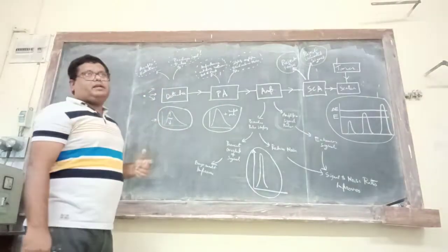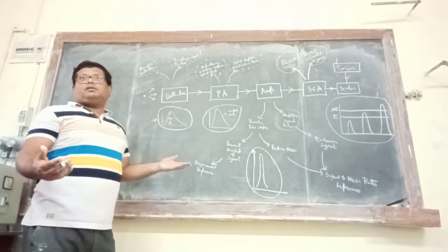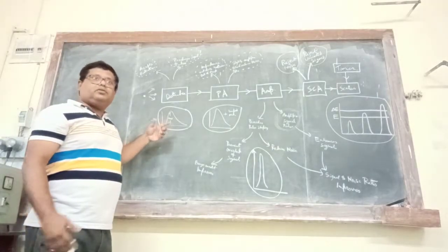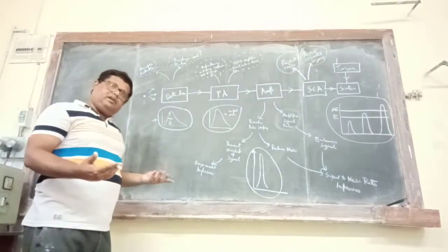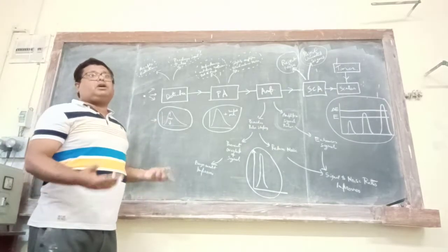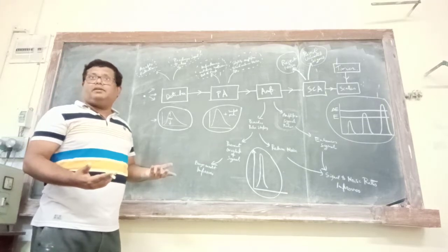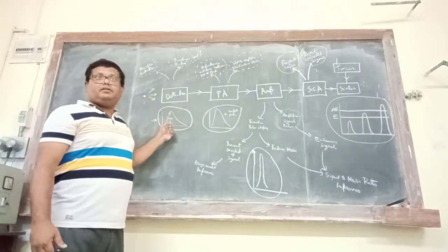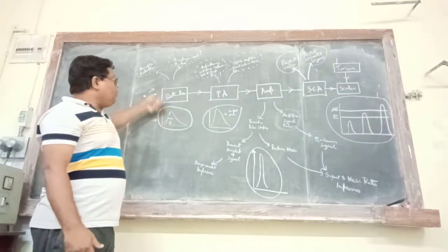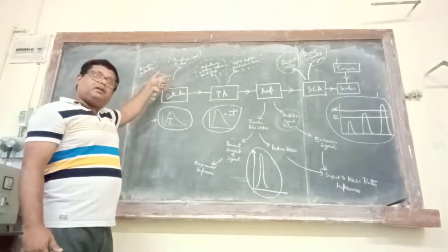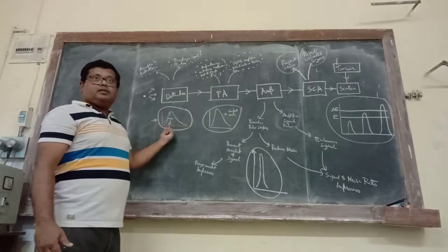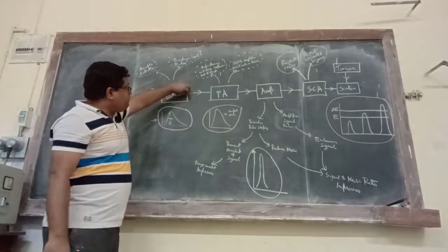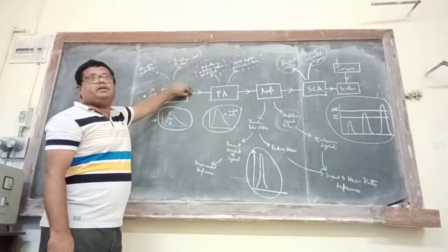Now the next part, what should we do? Come on, amplify the pulse so that we can use it. At least voltage order, so 1000 times magnification is required, right? That means millivolt to volt. We have to amplify it. That means I have to increase the y-axis of this pulse. But remember this part, the width of the pulse, and also the very fact that this output impedance is very large.